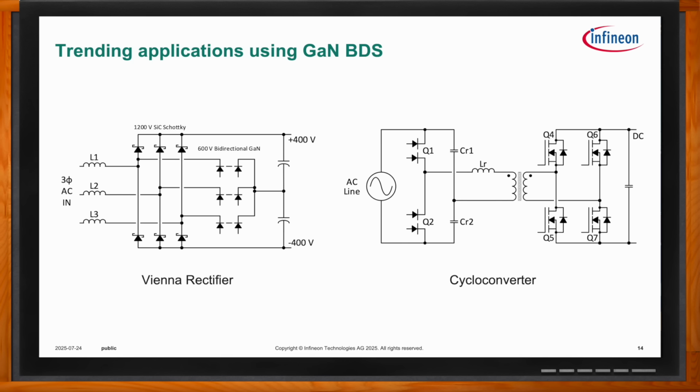Eric, you mentioned bidirectional power flow for the cycloconverter. Is that a result of using the bidirectional switch? Really, no, it's the topology itself. Remember, I could use a two switch approach here. It doesn't have to be a GaN bidirectional switch. I could use a two switch AC switch, but there are also topologies that have bidirectional power flow that only use unidirectional switches, not even an AC connected two switch approach. Those are separate concepts. Bidirectional power flow can be done with a number of different topologies. In this case, when we say bidirectional, we really just mean the voltage blocking capability of the transistor.